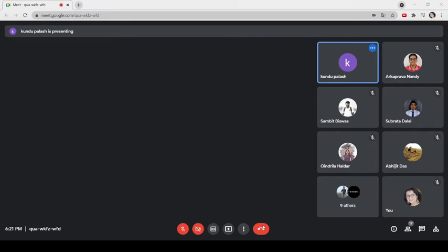Yes, if the C/T bit is reset, that is 0, the TMOD register selects the operation of the timer/counter unit as timer mode, which I have described. But if the C/T bit is set to 1, then it operates in counter mode. There is a difference between the counter mode of operation and the timer operation. That is why the internal timer is called the programmable timer/counter.